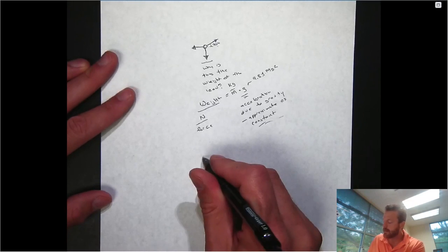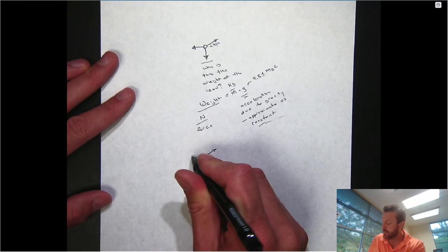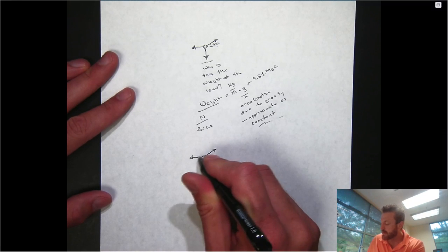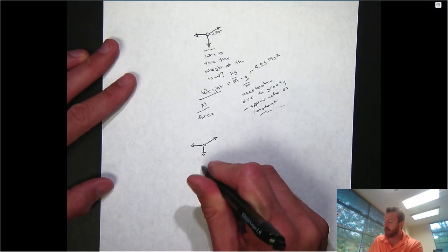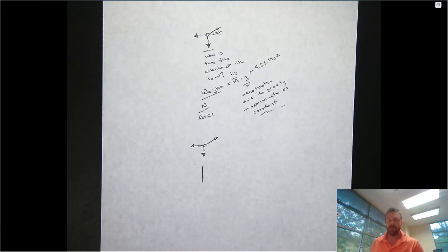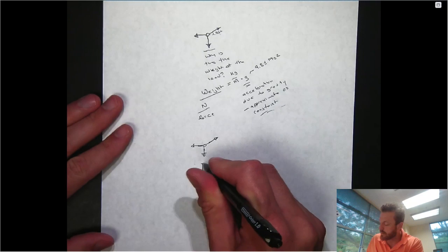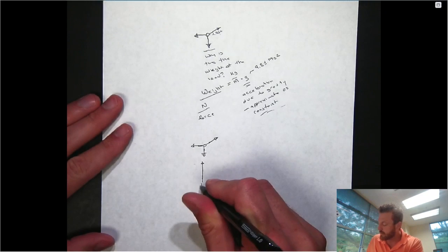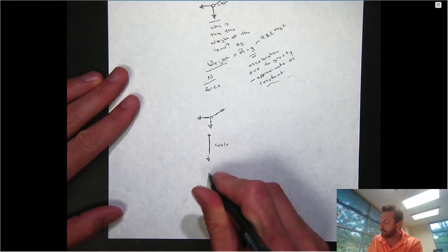Well, remember the idea that I said, if an entire system is in equilibrium, that means each of its pieces and parts is. So let's use Newton's law again and focus on the fact that really what we had here was a cable. And back to our earlier chapter 3 material, we know the cable can only support tensile forces. So here's our cable. And then we had that load here as well.